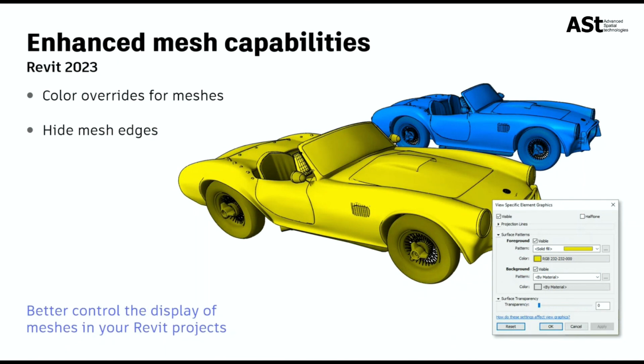There are also new capabilities for managing the display of meshes. You can now override the colors on the meshes just as you can do with solids. The solid fill pattern foreground color overrides now work for meshes similarly to fabrication parts. Revit 2023 also improves the appearance of newly imported meshes by hiding their internal edges.